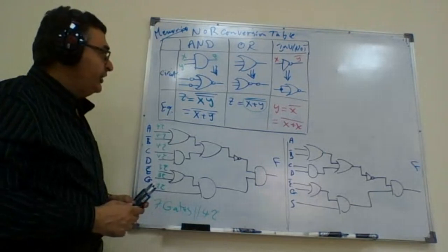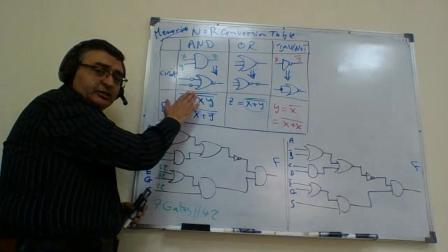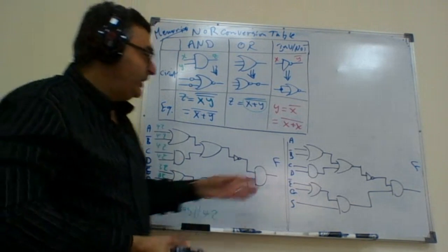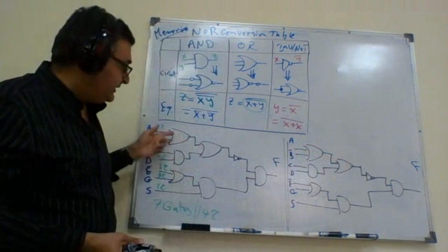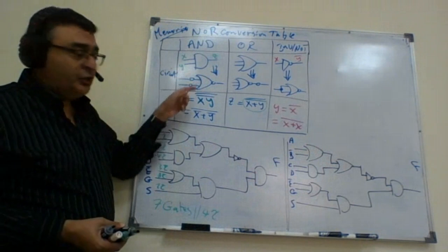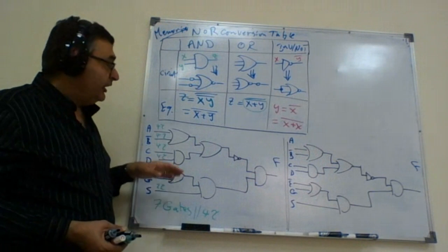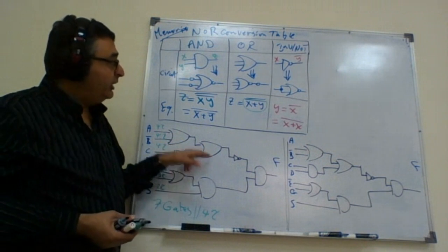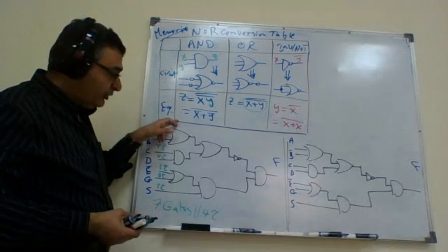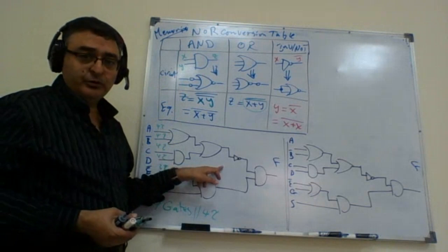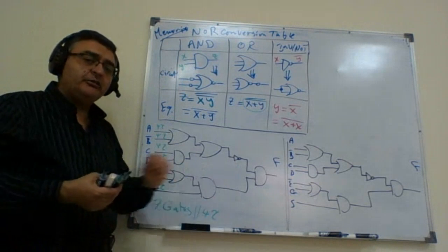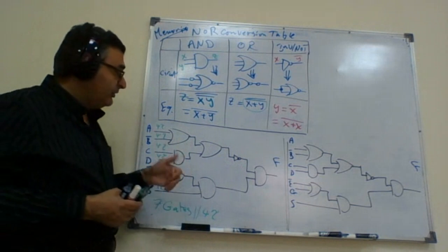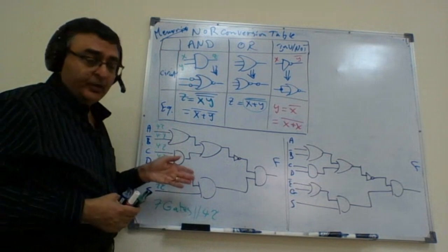If you are memorizing this table, it is very easy to just go and replace any of the logic gates that you have with its equivalent. We want to replace any OR, any AND, and any inverter with a NOR. My recommendation is to leave the inverters till the end of the work. Start with the ANDs and the ORs.